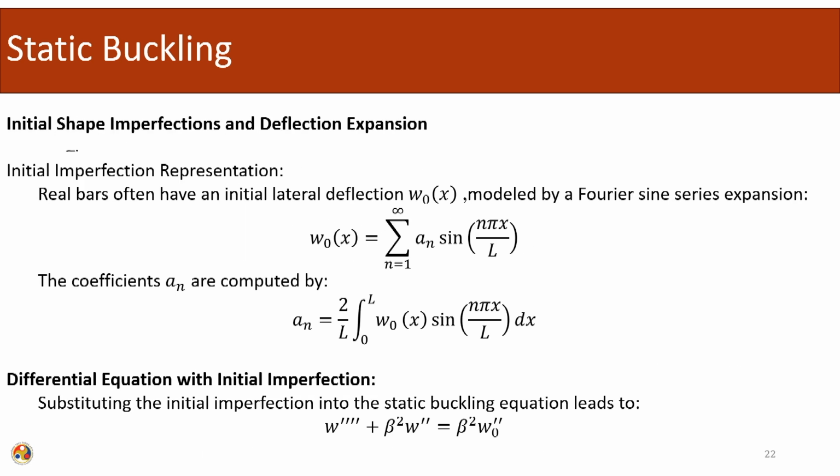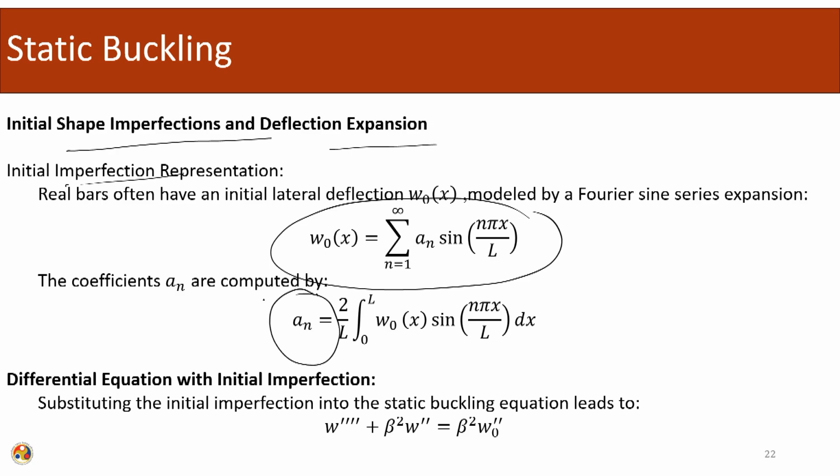So we dealt with the initial shape imperfection and the deflection expansion. The initial shape imperfection we modeled by a Fourier sine series approximation, and we calculated the coefficient.